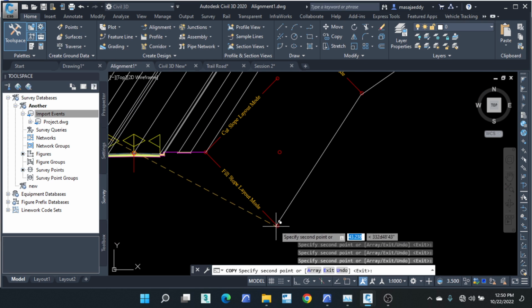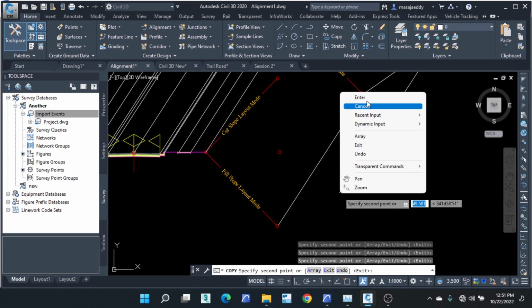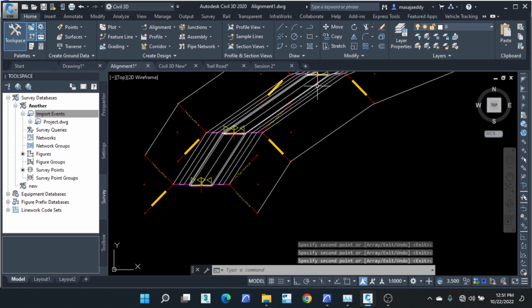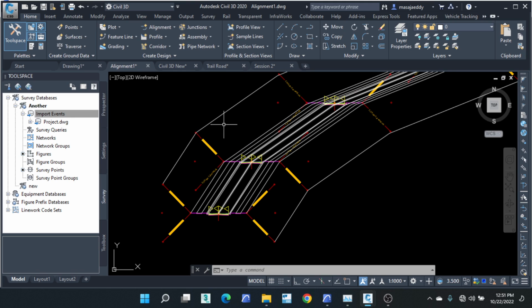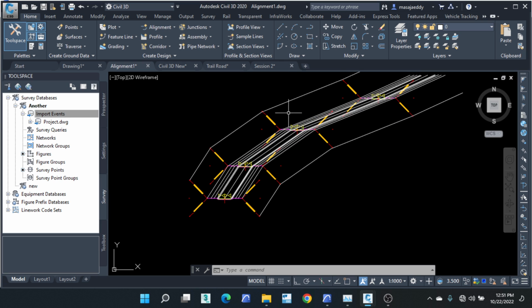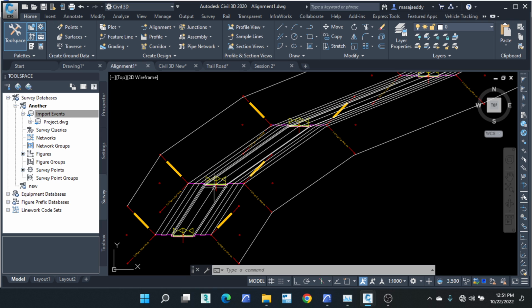So what you're seeing typically as a corridor created is just interconnected assemblies. You see this? So the frequency is the distance between these, that is what they call a frequency. Now the more they are together, the smoother this is. If they are further apart, this just creates sharp corners. But if I put them closer and connect all of them, they create something smoother. So generally, this is what a corridor is. You're just having assemblies connected to one another.